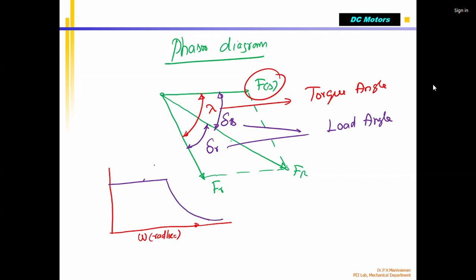Okay, this is the TE, torque generated by the rotor. After that, you have frictional torque, bearing torque, all those things going to consume. Resultant torque only going to drive the load. Okay, that we'll see. So then, as a synchronous speed, already we see that this speed is called as W base.